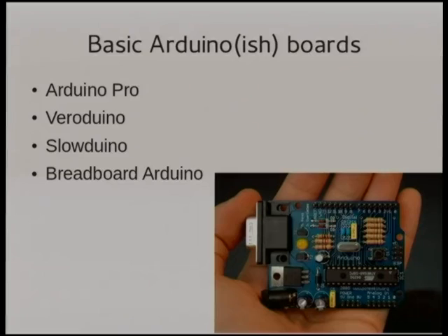For the most part, no, but the last one really caught my eye: the Breadboard Arduino. On the Arduino.cc wiki, there's a page about how you can actually use a breadboard with little 0.1 inch spaced pins in it. You can just put an AVR chip in there, put all the supporting infrastructure around it, and then build your own Arduino like that.